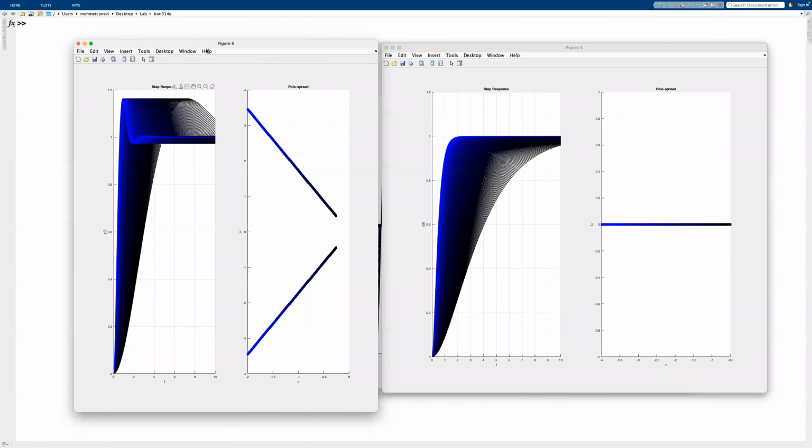There we go. Now we can see that here the behavior doesn't change. It's almost a 3D graphic now, where it is just shifted. And this is also the reason why we call these omega n values the natural frequencies, because the frequency is only changing, but the shape of the response stays constant.